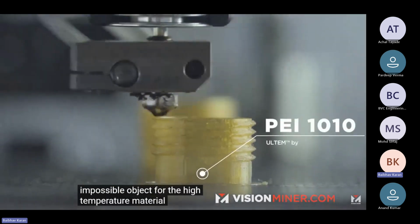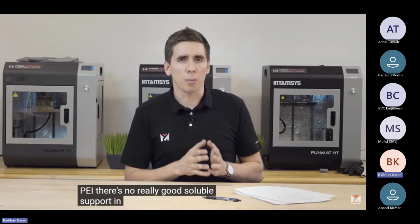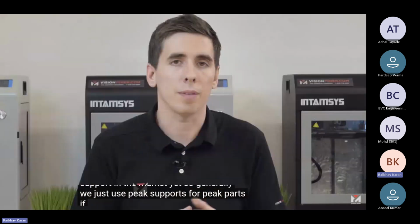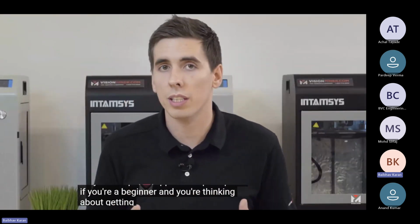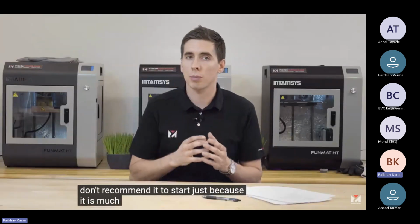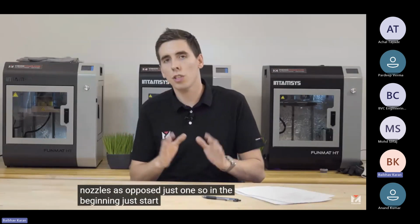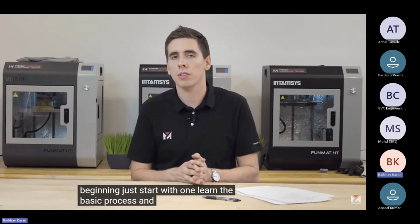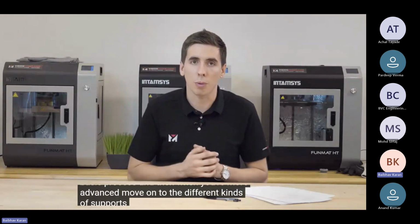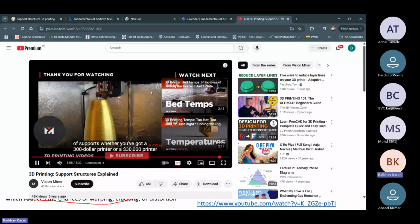For the high temperature materials like PEEK and PEI, there's no really good soluble support on the market yet, so generally we just use PEEK supports for PEEK parts. If you're a beginner and you're thinking about getting the soluble supports, I don't recommend it to start, just because it is much more difficult to tune in two nozzles as opposed to just one. So in the beginning, just start with one, learn the basic process, and then when you're more advanced, move on to the different kinds of supports. Whether you've got a $300 printer or a $30,000 printer, always.